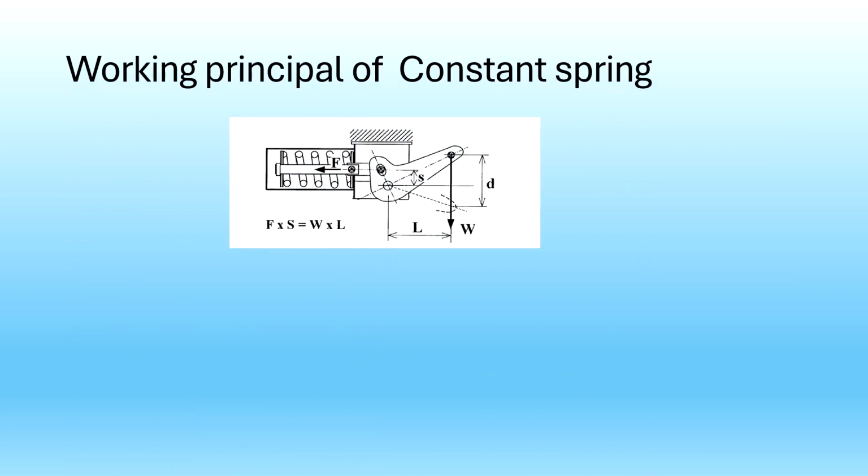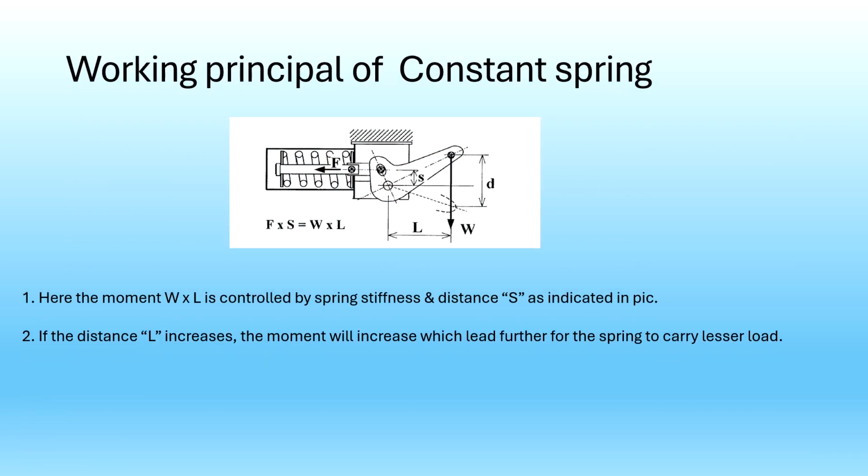Working principles of constant hanger. As the constant hanger will generally take a constant load, there won't be any variations. Once you set the load for 25,000 kg, then it will take a 25,000 kg load itself. We don't transmit any other load to any part, to any systems, to any nearby support or nozzles.